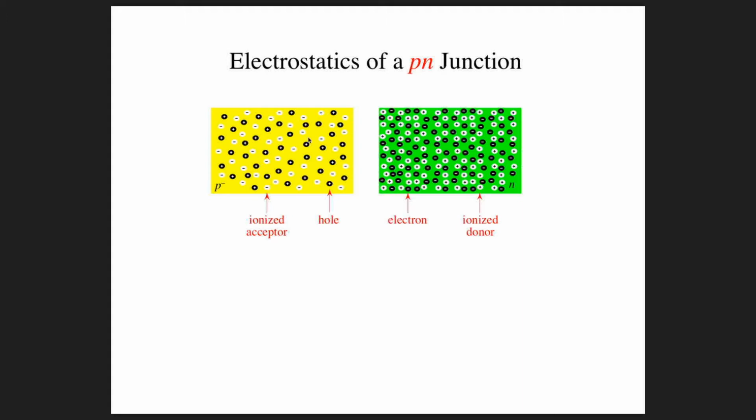And so here we have a relatively lightly doped p-type region and a moderately doped n-type region. So I've tried to represent that, although it's impossible to do so quantitatively, with the density of these black ovals and these white ovals here. So the white ovals with the minus signs and the white ovals with the plus signs are meant to denote ionized acceptors or ionized donors. So these are the space charges.